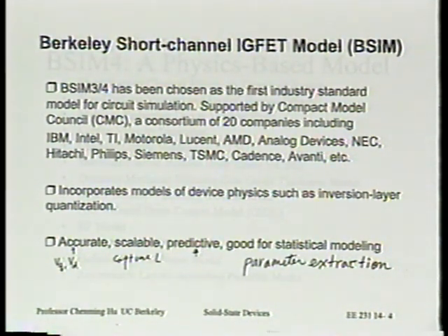turns out if you change this, let's say a particular device characteristic depends on 10 different parameters. As you change one parameter to change one device characteristic, it also affects other device characteristics. Can you see that possibility? Whereas if you really model this physically, of course, then that's no problem. You change the parameter, even T-ox, suppose you use that as a fitting parameter. No problem. You choose it to try to match the current. It happens to also match the other things fine. You know what I mean, right?